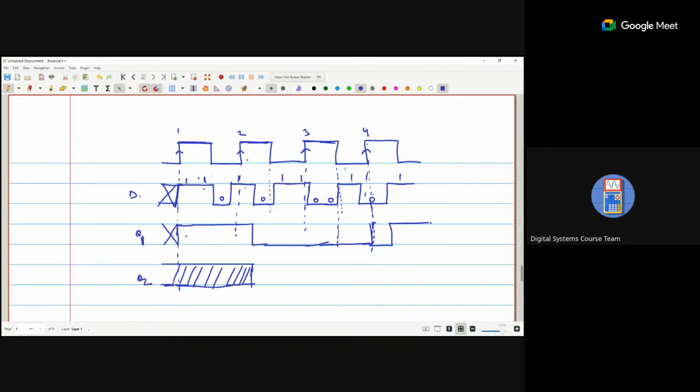So second clock and data is this one. So this data will go high. Third clock, high, then low, then continue. Fourth clock data is this way. Continue. So basically you can see that it will be shifted.